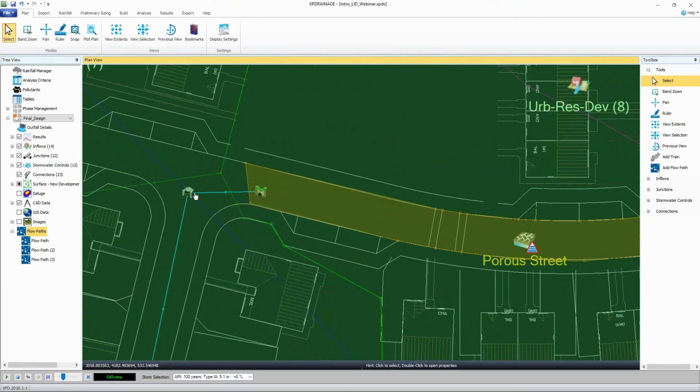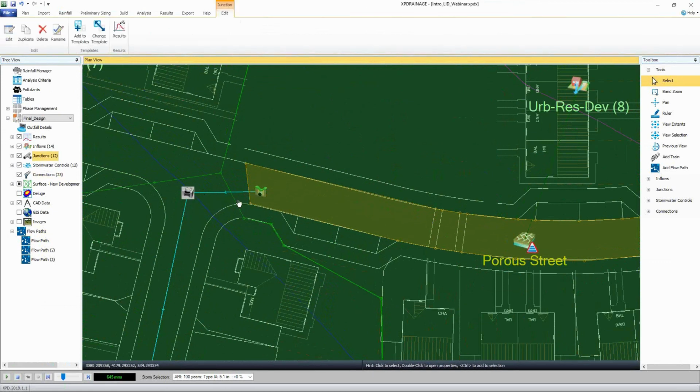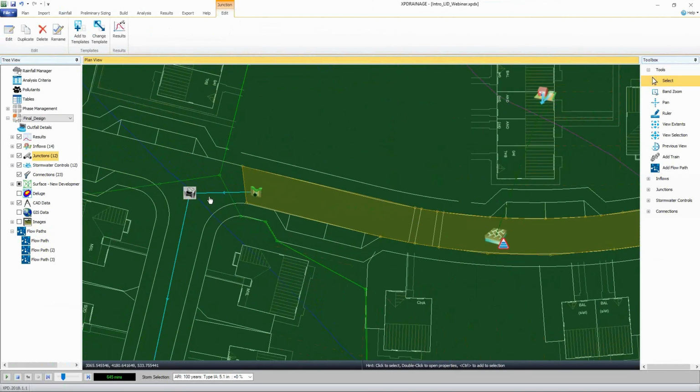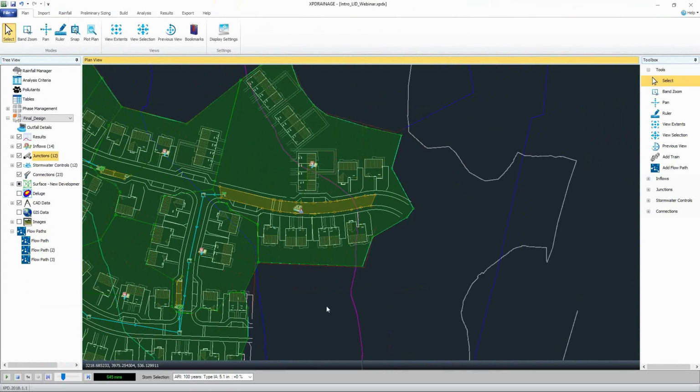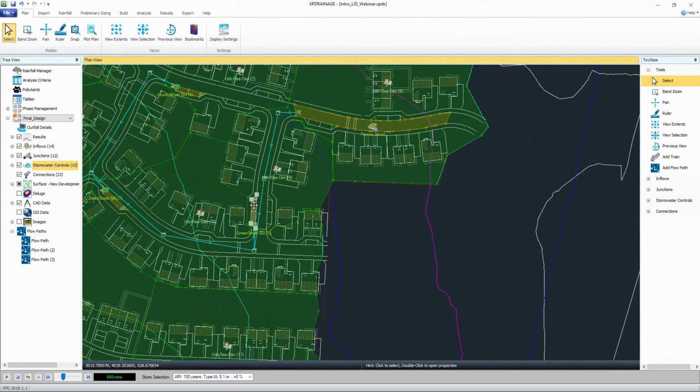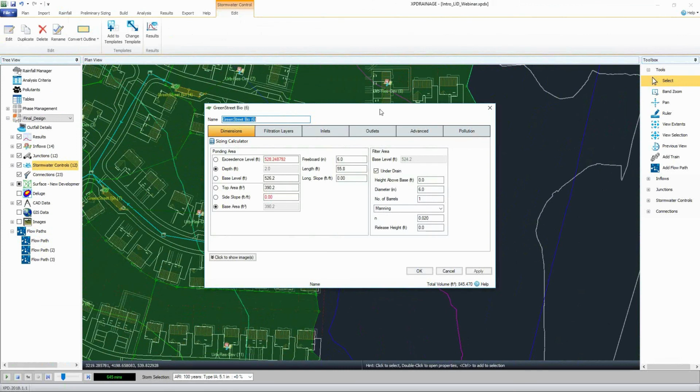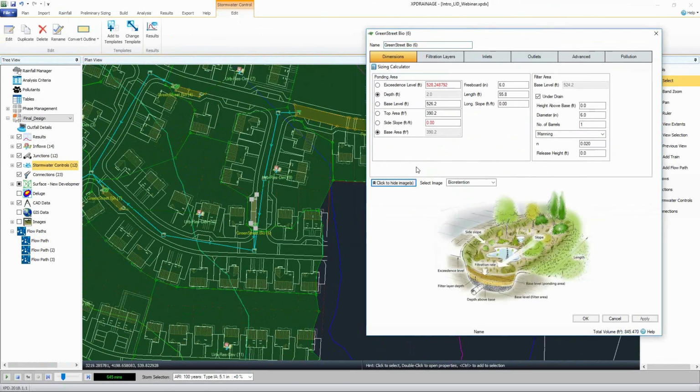Now, you know what? This is an under drain that connects into this manhole. These blue lines are pipes. Maybe let's add in some sort of inlet or some sort of bypass flow at this point in our system. It's a really common way to adjust and account for different systems in a network. Here happens to be a Raingarden, in all its complexity. Red numbers are something that I typed in manually. So the software updates items for me, but if I type in red, it will stick that number in there.